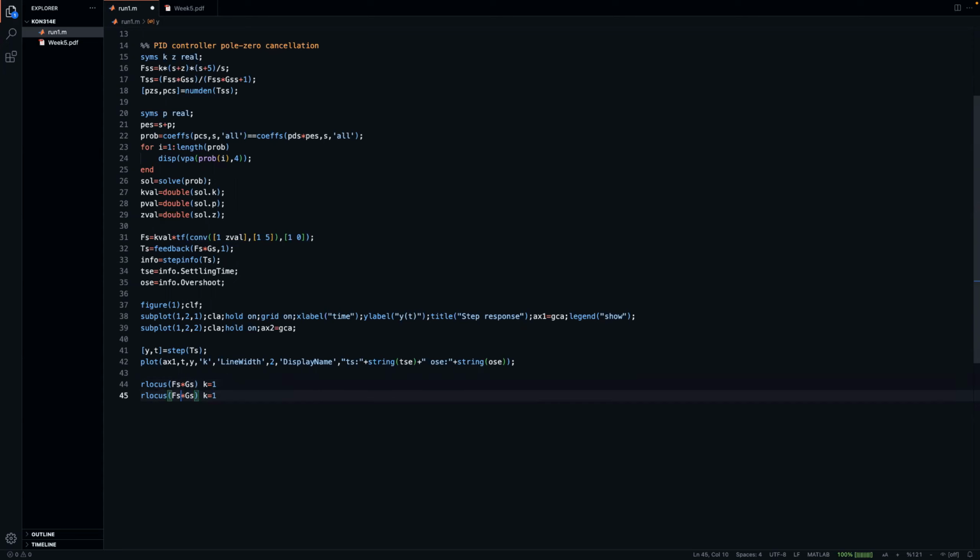That's one way of doing it. Or you can drop the kval part, so the dynamics. You add the dynamics only, and then you look for k equals kval. So you can do both. I'm going to choose the second one here. But by that, I mean, this is the dynamic part. So one pole at the origin, 1, 0 at -5, 1, 0 at -z val. So that's going to be added to the system. And when I click on the root locus and try to come up with a k value here, I'm going to click for k val. So this is still possible.